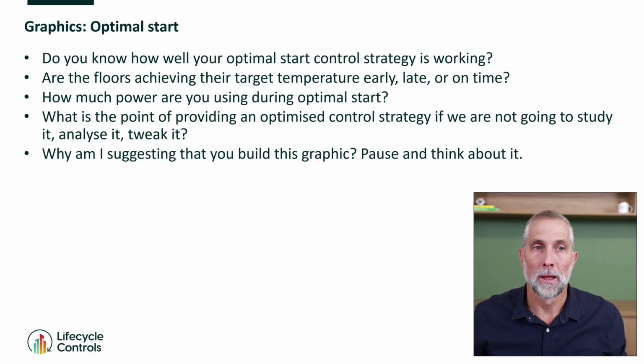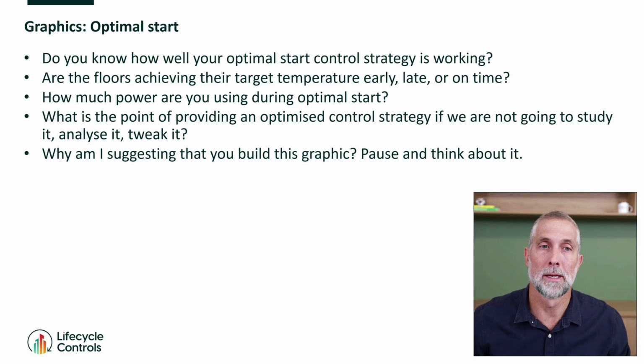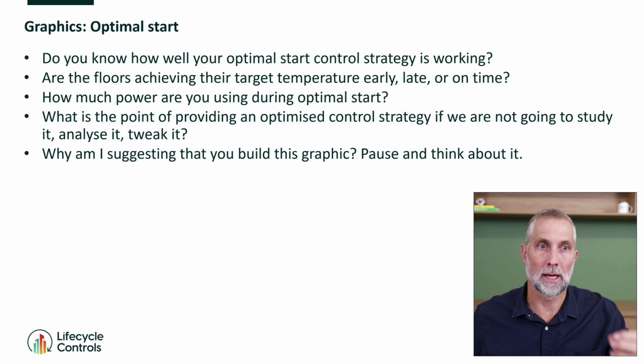And the second thing is we need to save energy, because obviously you could just say, look, we'll just start the building 4 hours early every day. Or if I exaggerate that, just run the building 24/7. If the building runs 24/7 or it starts 4 hours early, you're definitely going to have comfortable temperatures at 8 a.m. Absolutely. You've ticked that box, comfortable temperatures, but you're using a lot of power to do that. So there's always this trade-off for optimal start where you're thinking about, I need to provide air-conditioned conditions, comfortable conditions, comfort control, but by using as little power as possible.